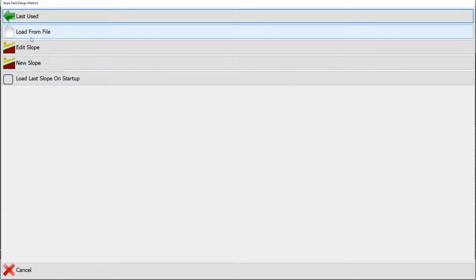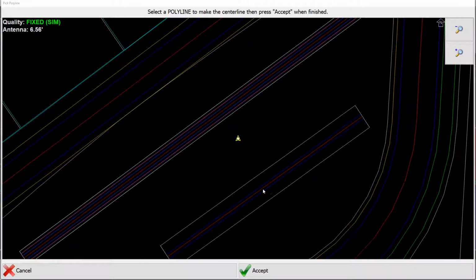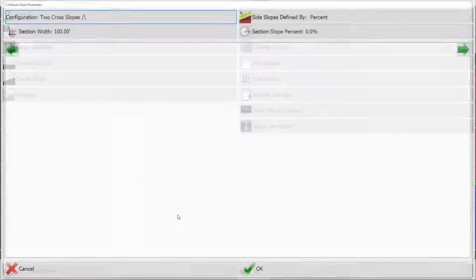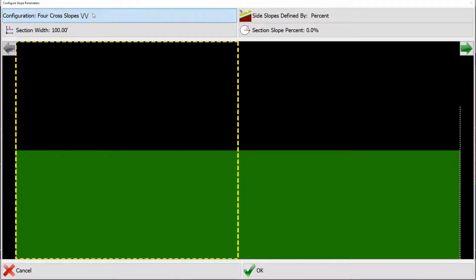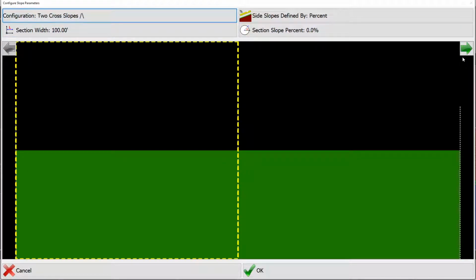Create Slope is another simple to use tool that will allow more complex designs to be made in the field. Here, we have allowed the user to first create a design by using a guideline to control slope bearing, grade, and main fall. The user can then choose what kind of crossfall by either percent or slope ratio. Not only can we choose that on one side of the guidance line, but we can add a crossfall percent or ratio on the other side of the guidance line. Using this, you can adjust the slope off of any line work you have loaded.